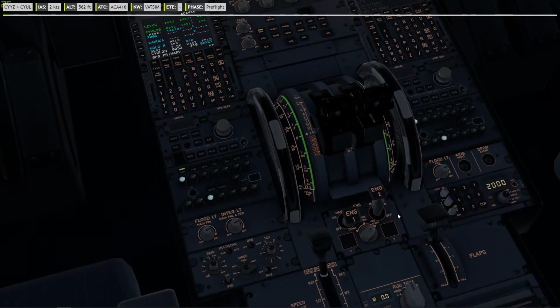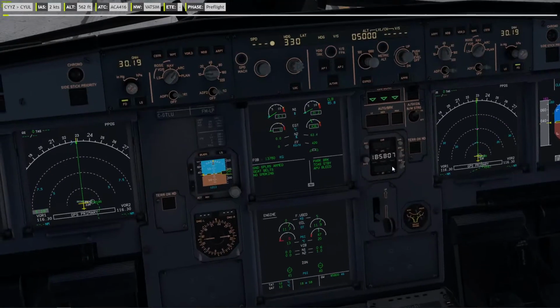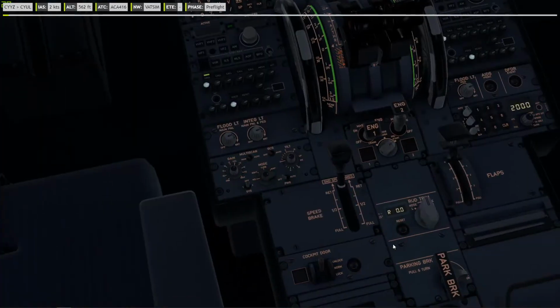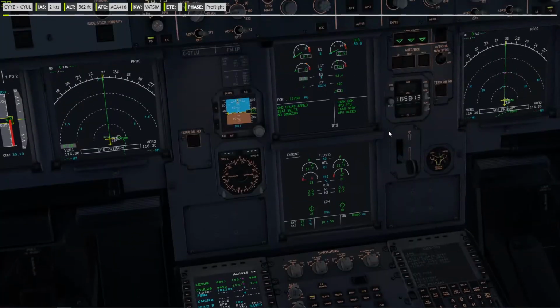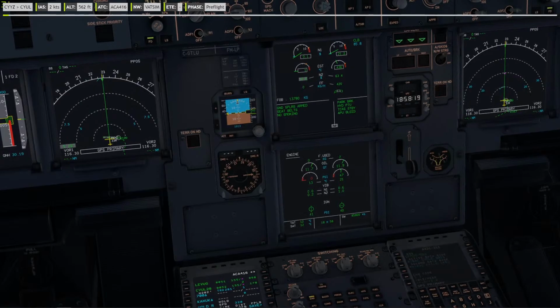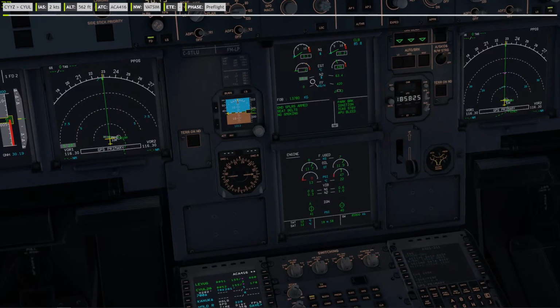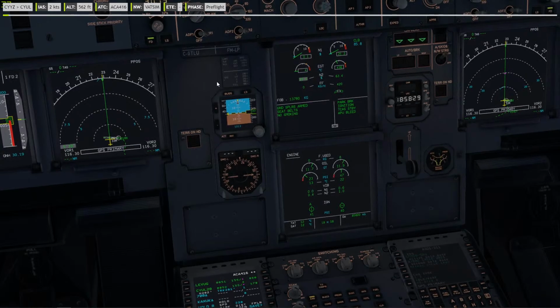That should probably go back to the off position. Tow is connected and bypass has been removed. Hand signal will be on the right. We'll see you next time and have a great flight. So there the second one goes. N2's rising. That should get 20%. Fuel should be allowed into the engine automatically, of course. We're in an Airbus.